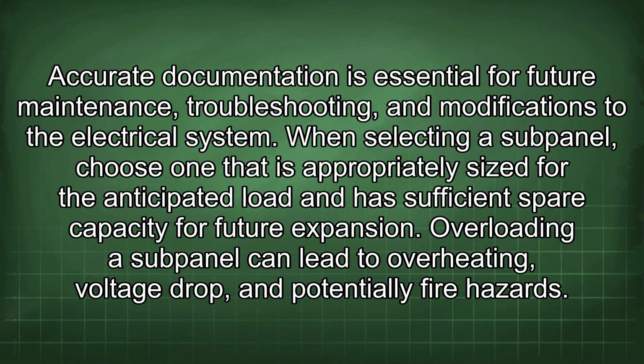When selecting a subpanel, choose one that is appropriately sized for the anticipated load and has sufficient spare capacity for future expansion. Overloading a subpanel can lead to overheating, voltage drop, and potentially fire hazards.